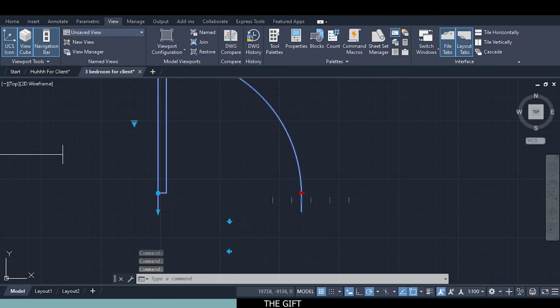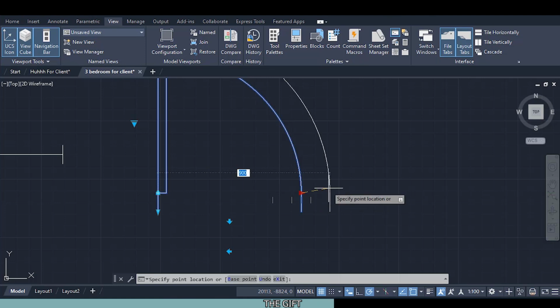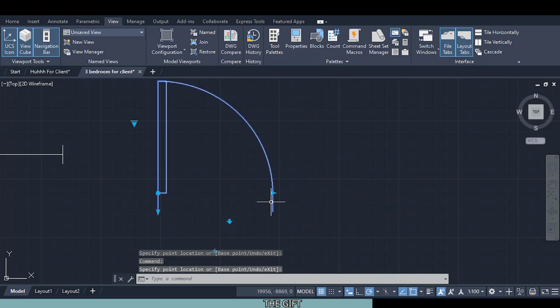And click on this grip. This is what is the most cool. Click this, as you can see, it's the same size as the door of our toilet because we are using standard. So now if you come this way, you can see there is a 700 type of door, there's a 600, 2 feet. If you're using imperial, that's what we'll be seeing. Come this way, we have a 900, which is 3 feet. Come this way, and with the control, if you click, it goes to any size.